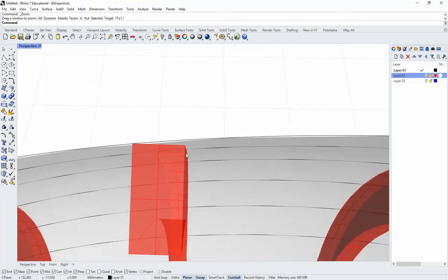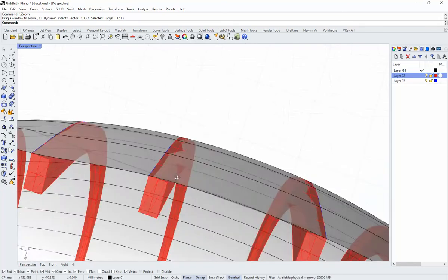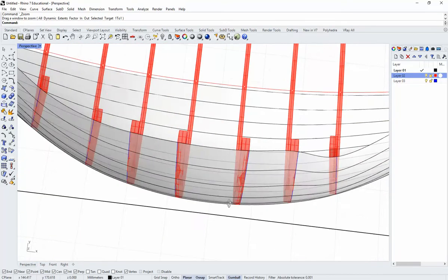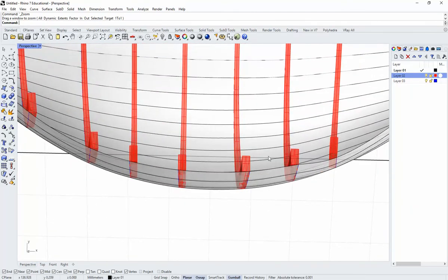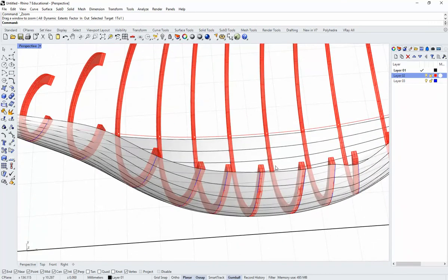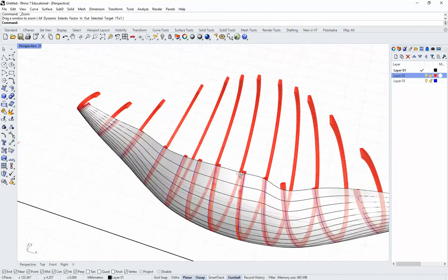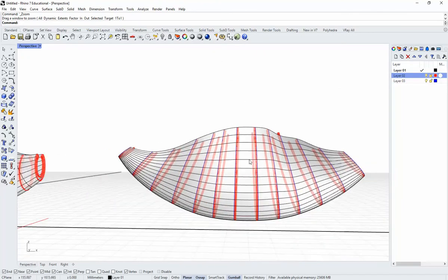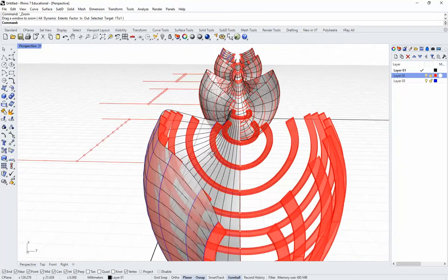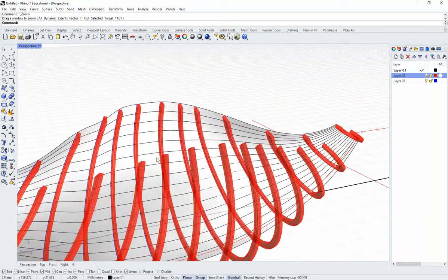But the solution's not going to be to use that curve. Really what we have is just the loft not being able to fully wrap those two there, and that's not surprising given the fact that they're almost parallel with one another. They're almost the same size, because in this case we didn't have a center rib, and that's just the way we built it. A center rib might actually be a nicer way to go here, but in any case, yeah, it looks like we also might even have a little waviness going on.